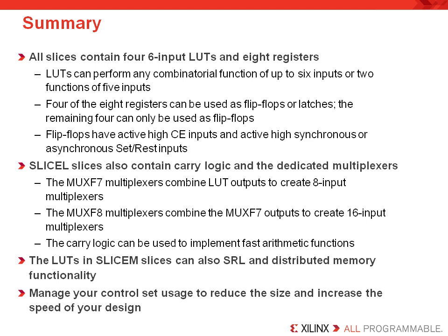There are a couple of different slices as well. Slice X slices also contain carry logic and the dedicated muxes. The MUXF7 multiplexers combine LUT outputs to create 7 input functions or 8 input multiplexers. The MUXF8 multiplexers combine the MUXF7 outputs to create 8 input functions or 16 input multiplexers. The carry logic can be used to implement fast addition, subtraction, and comparison operations. The LUTs in the slice M can also be used as shift registers or 64-bit distributed memories. And finally, manage your control set usage so you can reduce the size and increase the speed of your design.